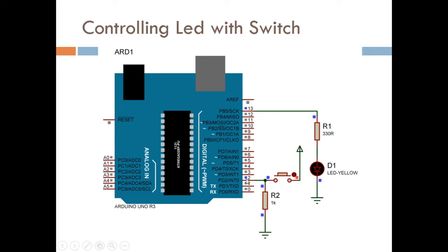So I don't know whether I am getting 0 or 1. Sometimes it will be read as 0. Sometimes it will be read as 1. But when I am writing a program, I cannot write like this. I can write only in such a way that I can check for either 1 or 0 in the program. So when I am pressing the switch, VCC will be going in, so I can check for 1 because I am getting 1. But when I am releasing, somehow I need to get 0 in pin number 2. Then only I can write a program accordingly.